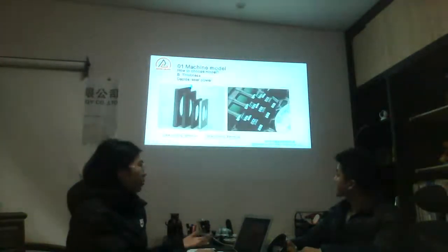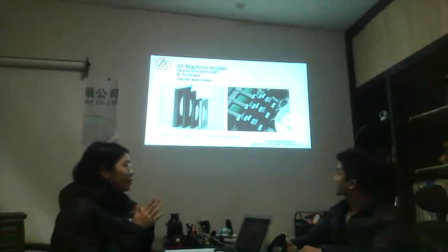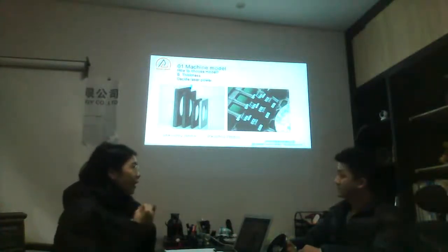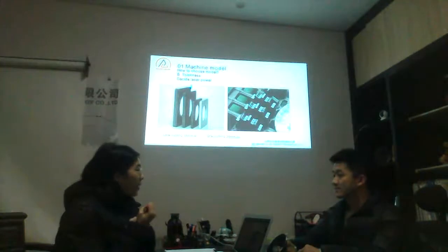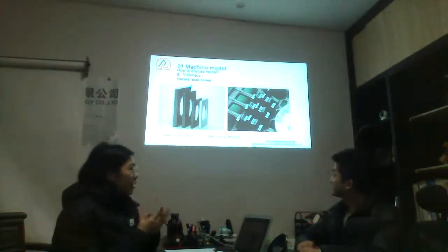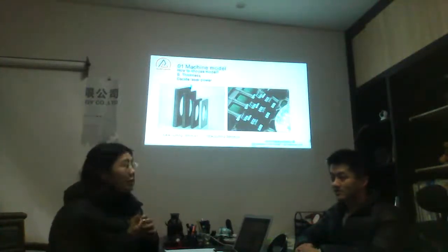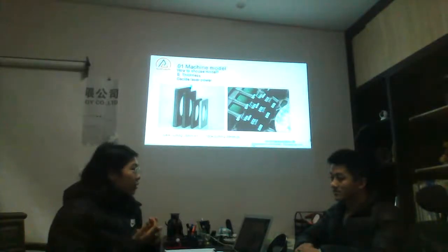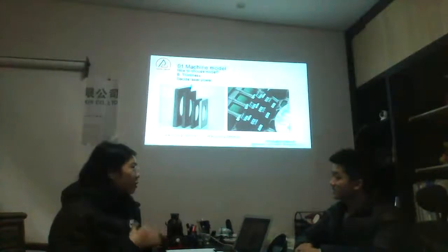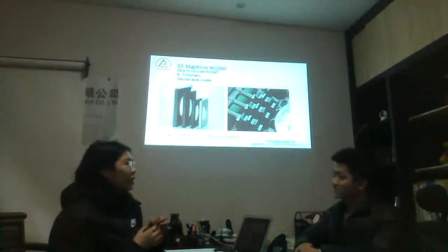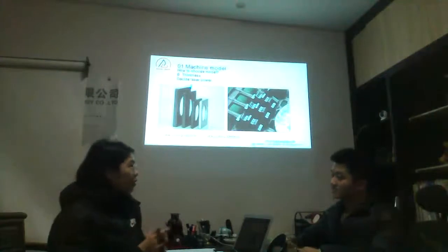So the first thing is we need to confirm the materials with our bosses. And the second one is the thickness of the materials or workpiece, to confirm in advance so that we can recommend the right laser source with the machine.